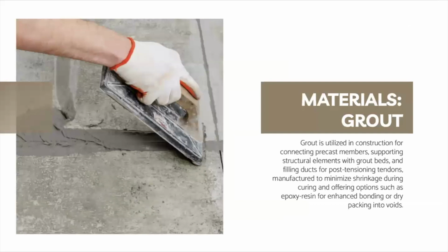So the next material is grout. Grout serves multiple purposes in construction: connecting precast members, supporting structural members with grout beds, and filling ducts for post-tensioning tendons.